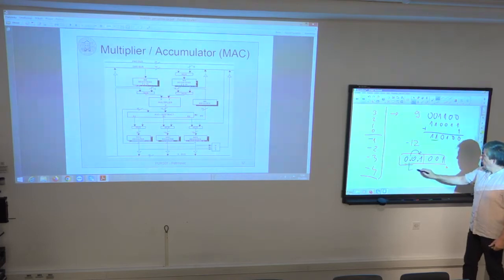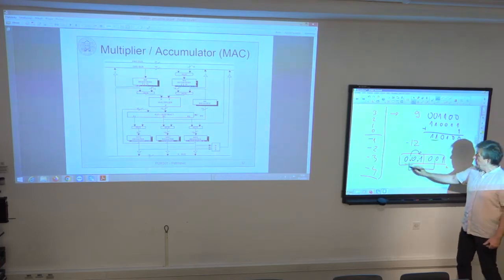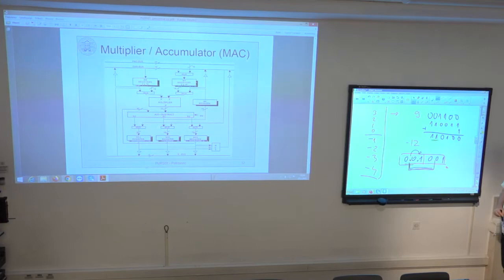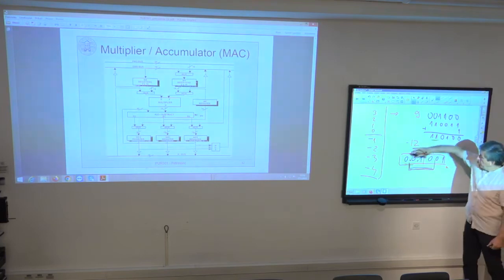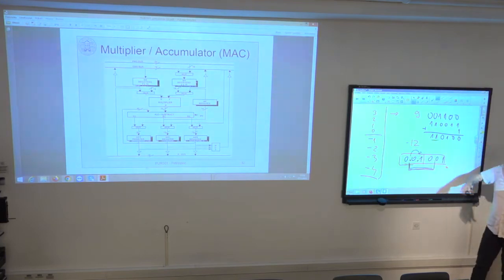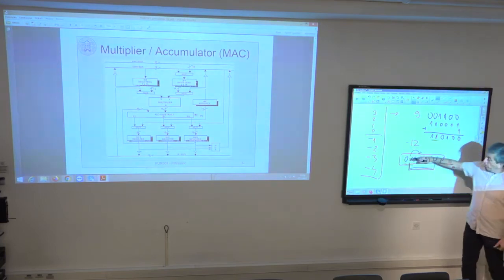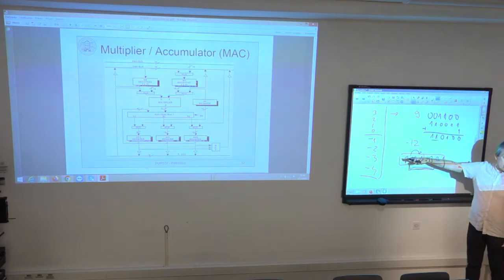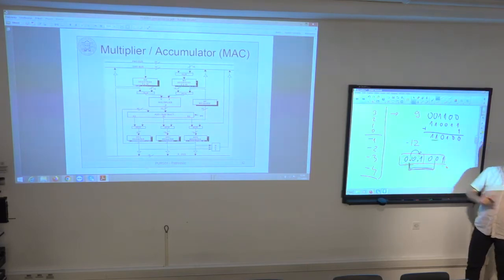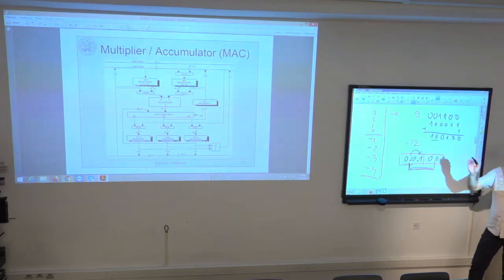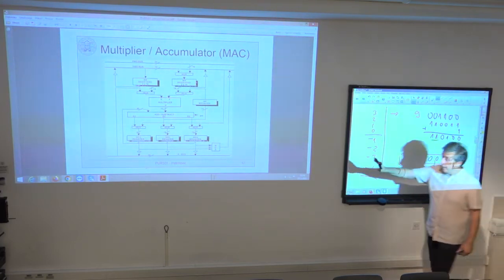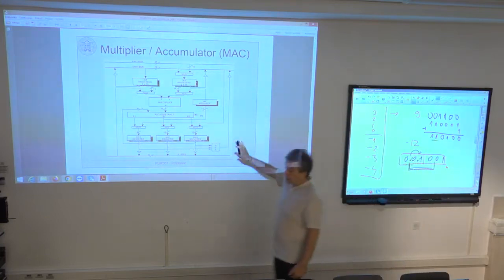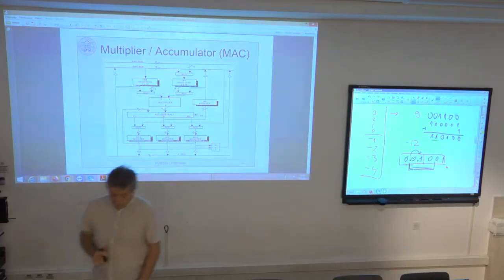This would be the proper interpretation of the most significant word of the product if I only have to take the upper word. So not this, but this. And to have this, I can simply shift the product to the left by one position and then extract the upper word. And it is done automatically in hardware.